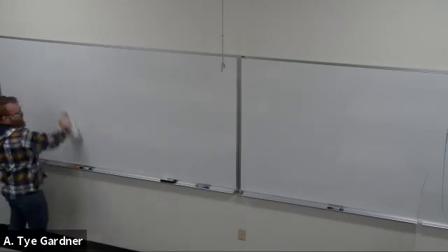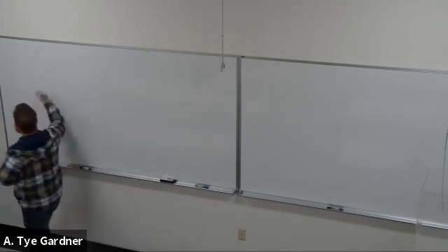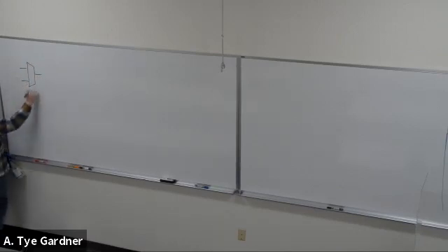Now, I've mentioned them before. They are called multiplexers. Multiplexers are really quite simple. This is your multiplexer schematic. For your ports, we can call this, say, X, Y, and S. In this case, S is not sum, S is select. Okay? I'm going to call the output port F. Now notice at this point, I'm not labeling the connections to it. I'm labeling inside this block. Just like that full adder block diagram, the ports have a name, okay?